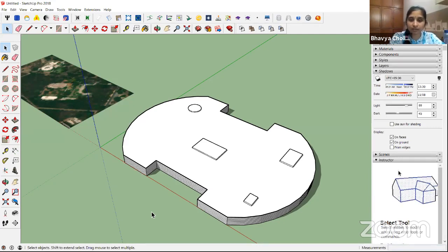That is the reason we always want a no-shadow region at the respective location. Simply, that is why in SketchUp we do the shadow analysis first, and then remove the external part where the shadow is falling, and use the other areas for solar. So you check the layout consideration in that aspect.